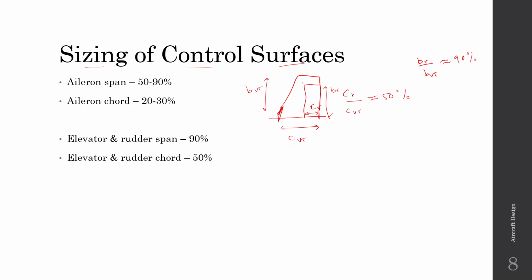So there is something called control surface balancing, where we either put the hinge line a little bit over here, not at the edge, which reduces this control stick force, or we might have a control surface like this.